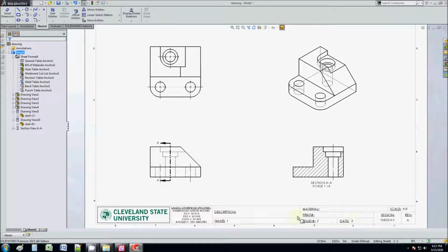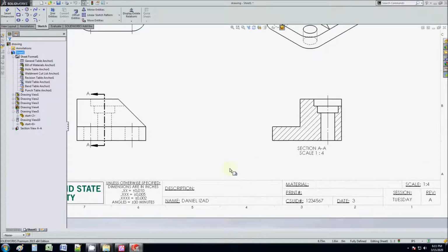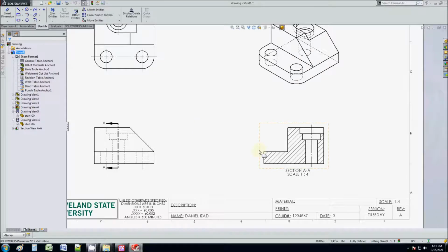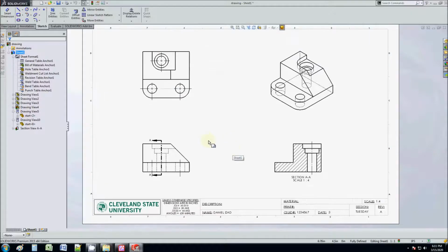And then before we forget, let me update the template below, file properties. Okay. So it's usually best to keep capital letters in mechanical drawings. Again, it's all about clarity. Remember, we're using sans serif fonts. There's no serifs in this font. It's just supposed to be very easy to read. Again, it's all about clarity. It's a very technical drawing, and the whole purpose of this is so that you get this object back exactly the way you wanted it to be without any errors.